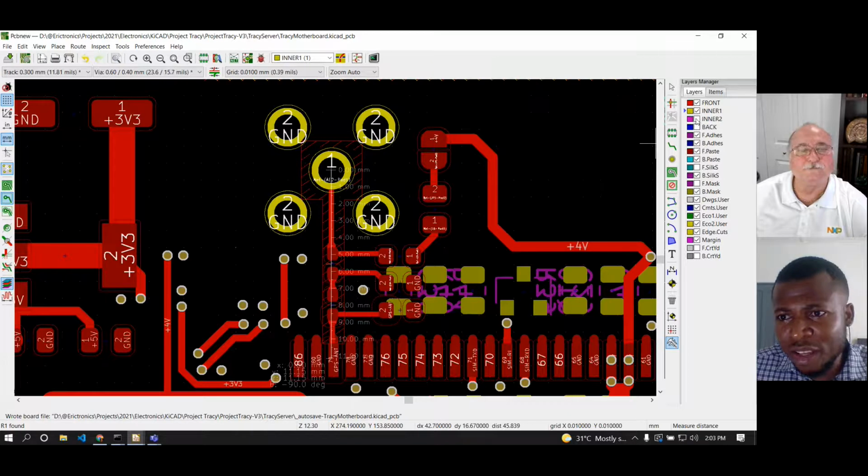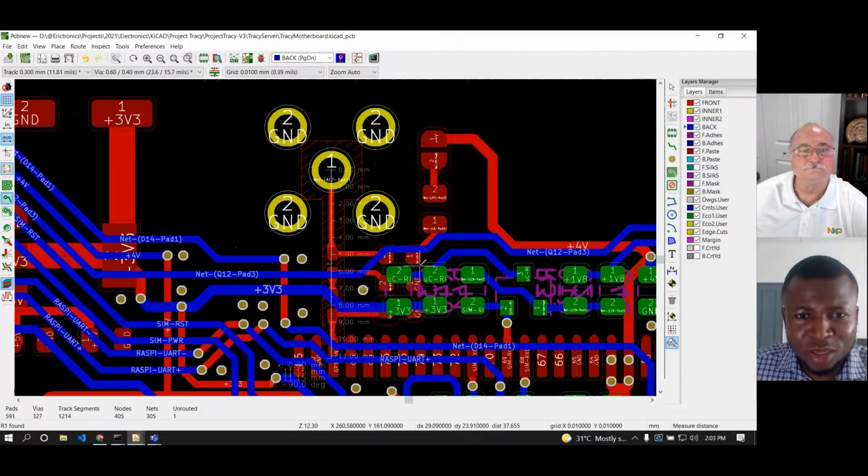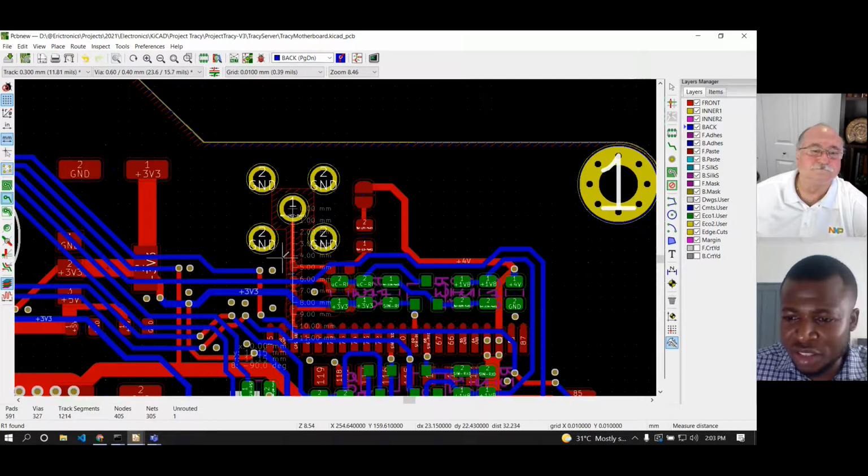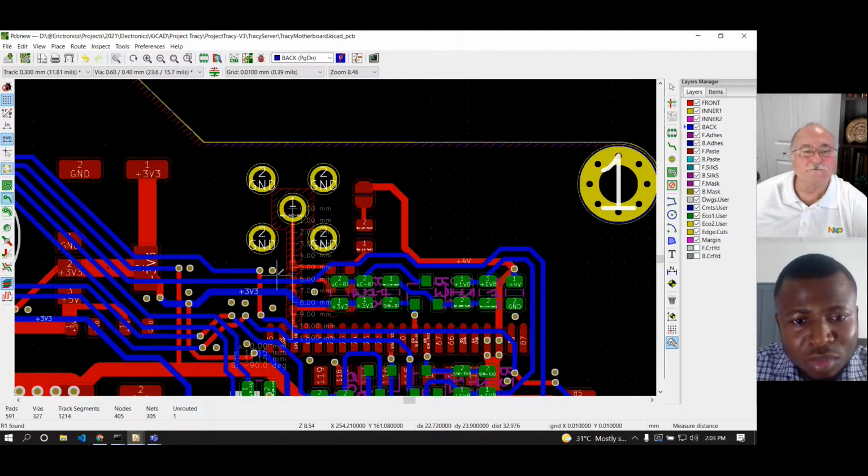Yeah, I think I actually checked that. Around the connector, there is no route. The routes here are on the bottom and it's shielded by ground planes, so they're not even close to what you're doing. All the radio traces are on layer one, adjacent to layer two. They are happy little traces.